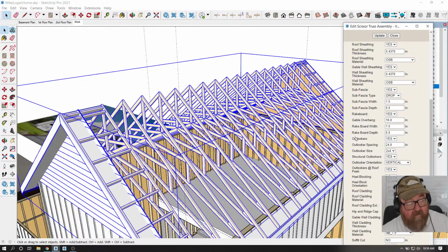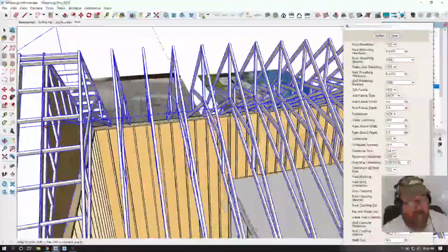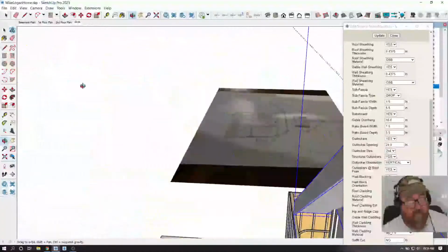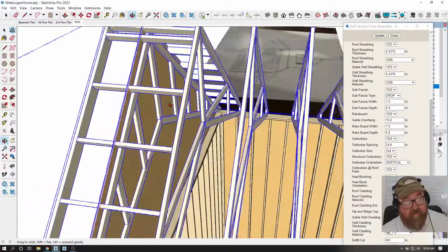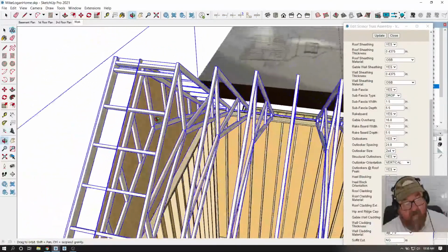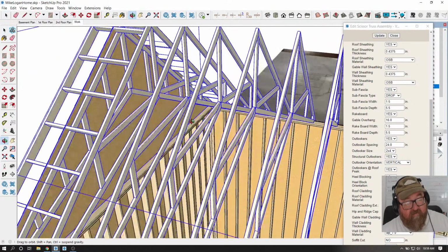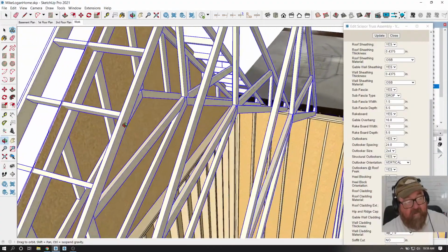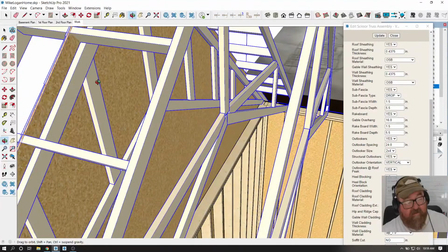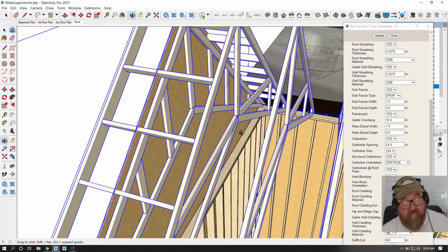See, what you can do is have the truss company drop this. Now, this gable truss shouldn't be a scissor truss. The gable truss should be a regular truss that comes all the way down to the bottom, so I'll have to deal with that. But if you drop this house line truss, the one on the end, it's non-load bearing.